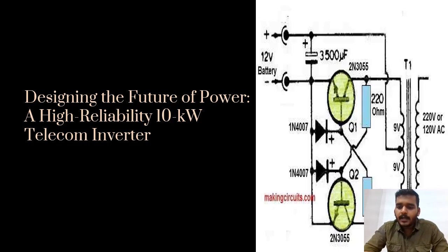Firstly, the transformer: 220 volts AC to 120 volts AC, with a 9 volt, 9 volt output. It is a midpoint center-tapped transformer with the DC supply and a capacitor of 3500 microfarads, and we can see the resistors connected in parallel and the 1N4007 diodes, which act as gates. We can see the circuit components here.